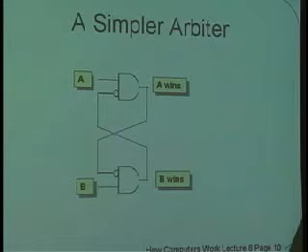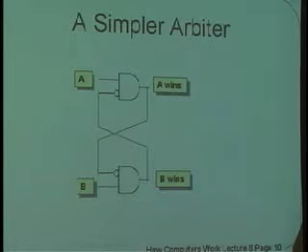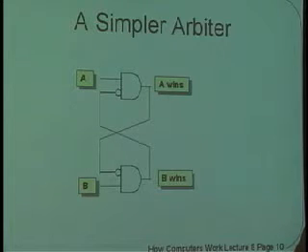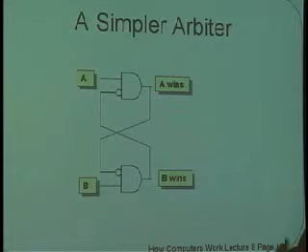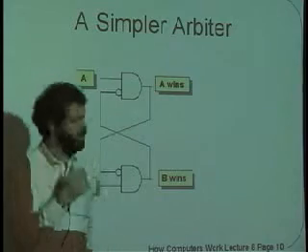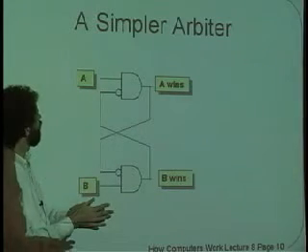Well, it turns out that an edge-triggered flip-flop is a more sophisticated version of an arbiter than we actually need to build in order to solve the problem. And so I'm going to take this one notch down and go back to our fundamental mode state machines. If you remember, we talked about D-latches and set-reset flip-flops. Well, this is actually a version of a set-reset flip-flop which is used to decide which one wins. And so just trace through a circuit with me here for just a second. This is what you might use if you're trying to decide a game show.